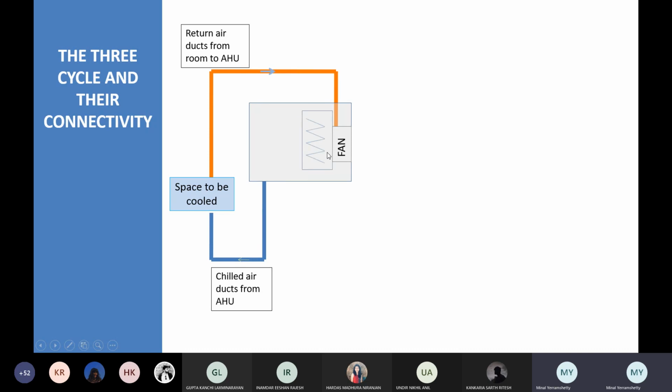Then the second part is the coil. Now this coil, okay, and then finally you have filter and you have humidity control. How do you control humidity? Say you are in Bombay and we have some 90-degree, 90% humidity with this kind of weather outside, and when we have such highly saturated humidity, what do you do? You will introduce some dehumidifier, right? You have these amazing salts that are there, or maybe a heat kind of a thing which will evaporate the whatever. Okay, so basically you are taking the humidity out of the air, then it gets filtered.